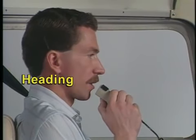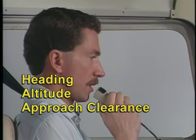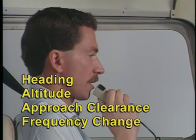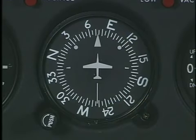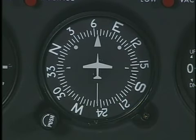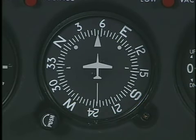This clearance includes 4 key elements. They are the assigned heading, the assigned altitude, a clearance for the approach, and the instructions for when to change frequencies. Normally, the final heading assignment allows you to intercept the final approach course in sufficient time to establish yourself on the course prior to the final approach fix.